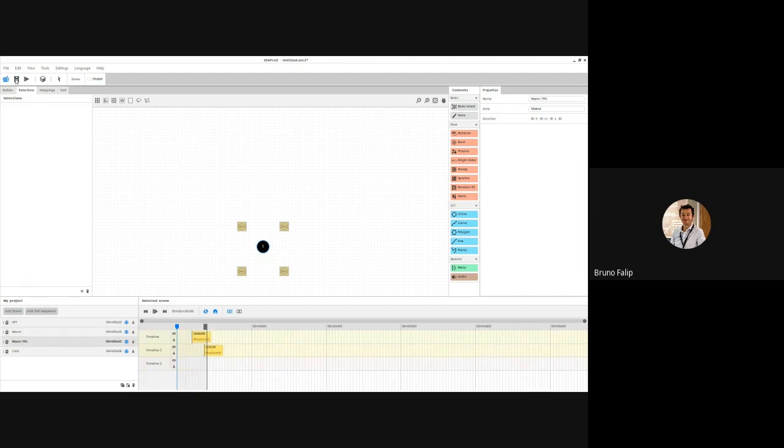There is one thing we recommend, which is to create a specific zone for DALI. Of course, if you are controlling DALI devices only, you don't need it. But if you want to use it as a gateway with DMX and DALI, it would be better to have one simple zone for DALI and the rest for DMX, in order to not mix DMX programming and DALI programming within the same zone.